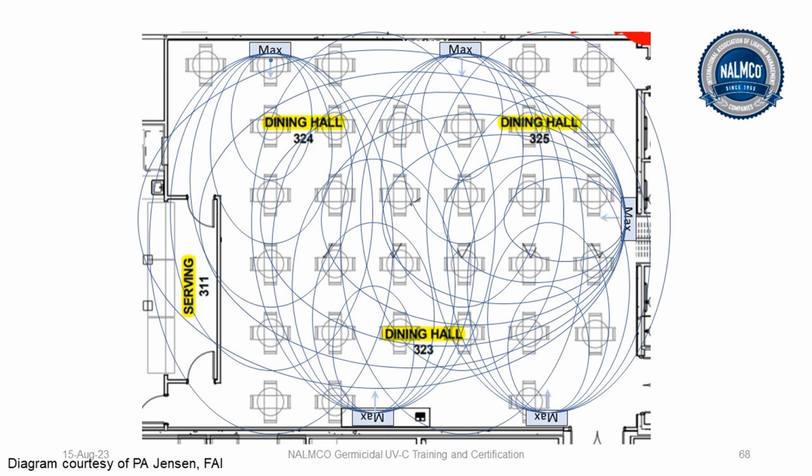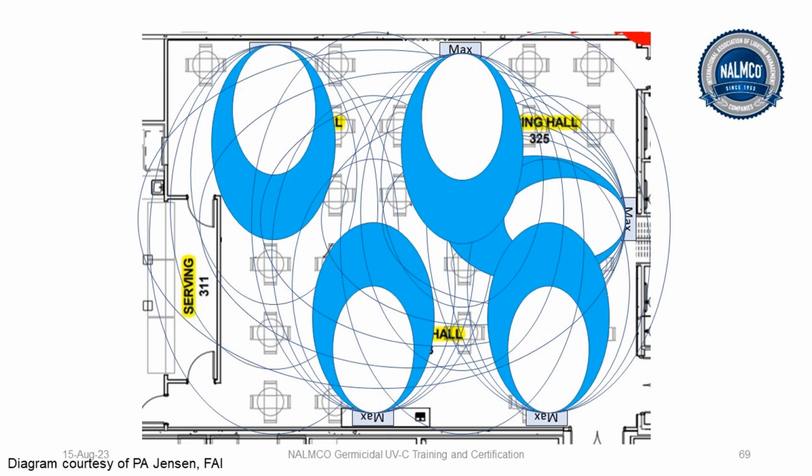So what did we do? We took a look at the ventilation system. It was strictly a 5-ton unit. We had them operate the fans while the spaces were occupied. So the heating and cooling would cycle on and off, but the fans themselves will continue to move air, and that will be sufficient for getting enough air mixing.